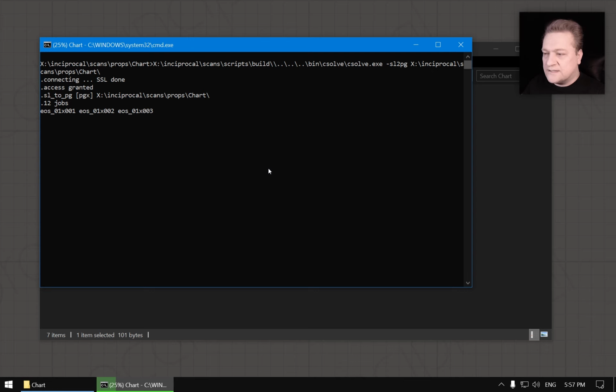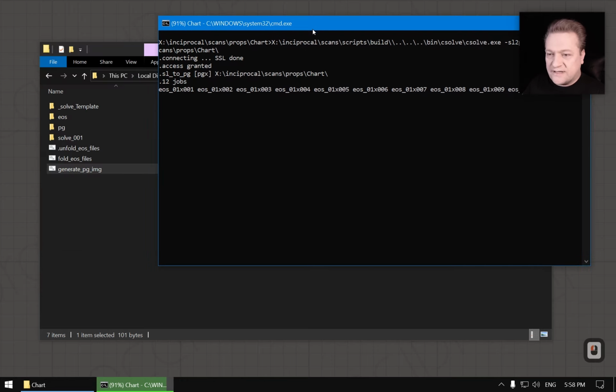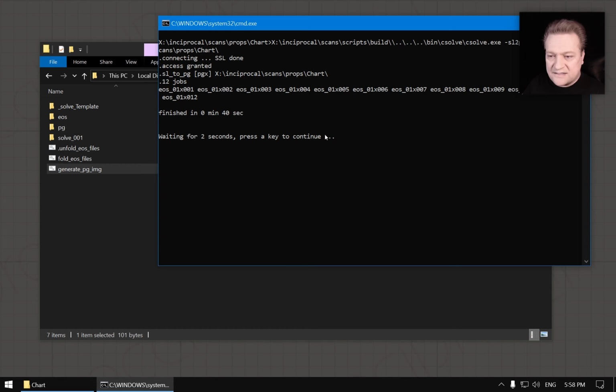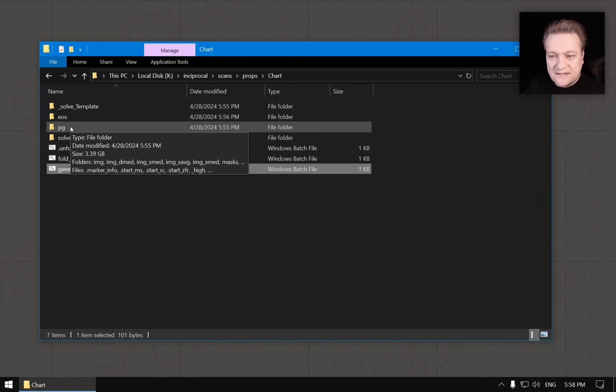This script does initial pre-processing and material estimation, and it generates synthetic images for the photogrammetry process that we use. Some images are optimized for the alignment process, where it tries to remove as many view-dependent and lighting effects as possible. Other images are more suitable for more accurate and higher quality depth map and geometry reconstruction. In this case, it's good to have a beefy CPU. We're using 32 threads because this can take a while sometimes.